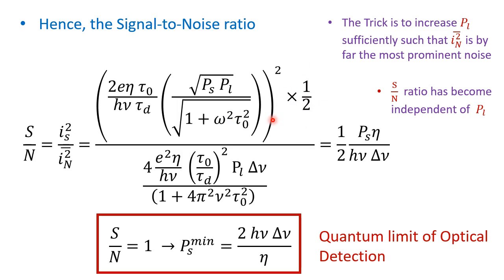And you see that if I'm looking at the signal to noise ratio, the noise is dominated by my DC noise, right? This is the expression that I have. Remember, I have said that PL is much larger than PS, so I neglected PS. You see, clearly every term in this perfectly gets cancelled. Lots of terms.